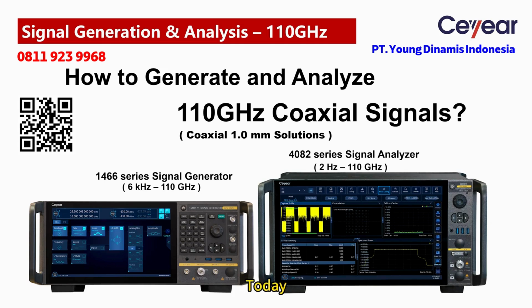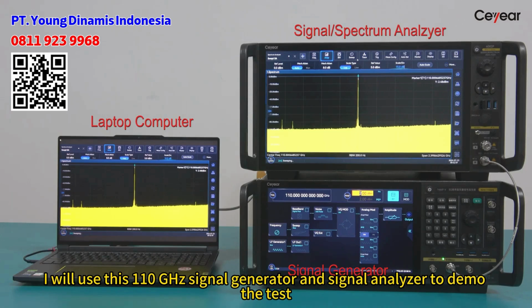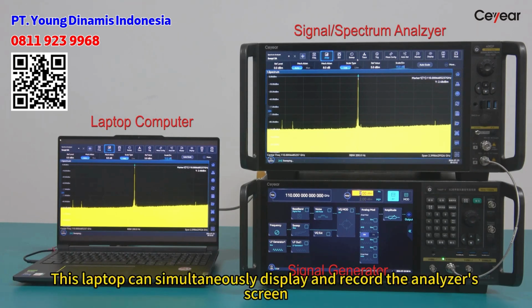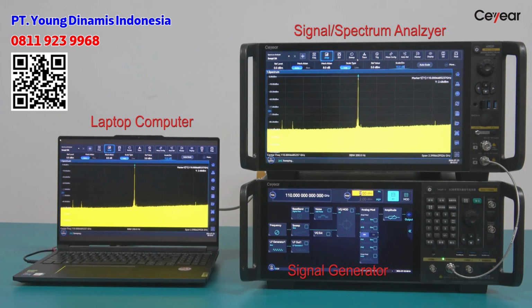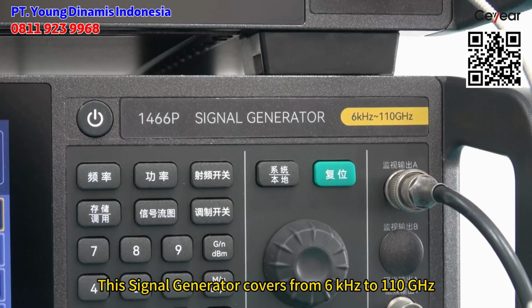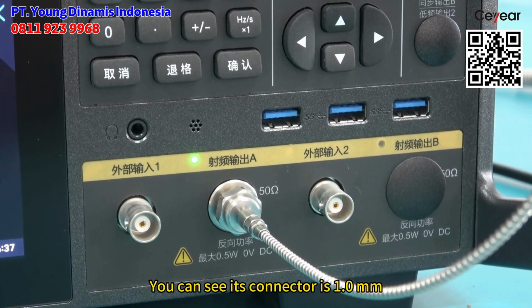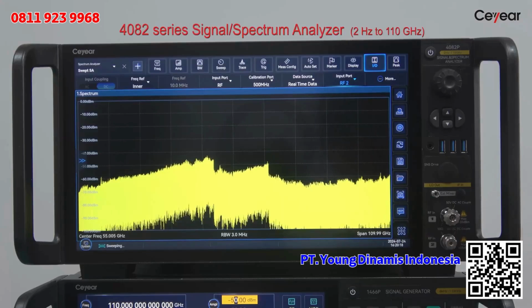Hi guys, today I will use this 110 GHz signal generator and signal analyzer to demo the test. This laptop can simultaneously display and record the analyzer's screen. This signal generator covers from 6 kHz to 110 GHz. You can see each connector is 1.0 mm male.